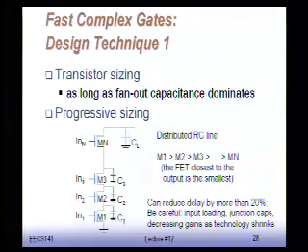Okay, so at this point, we have gone through all this analysis of how the delay depends on the size of the network, how to size the NMOS, the PMOS. What can we do for improving this, to improve the speed, okay? So the first thing that we can do has very much to do with this Elmore delay that I just mentioned, okay? And we have seen that if you think about how the Elmore delay expansion is derived,